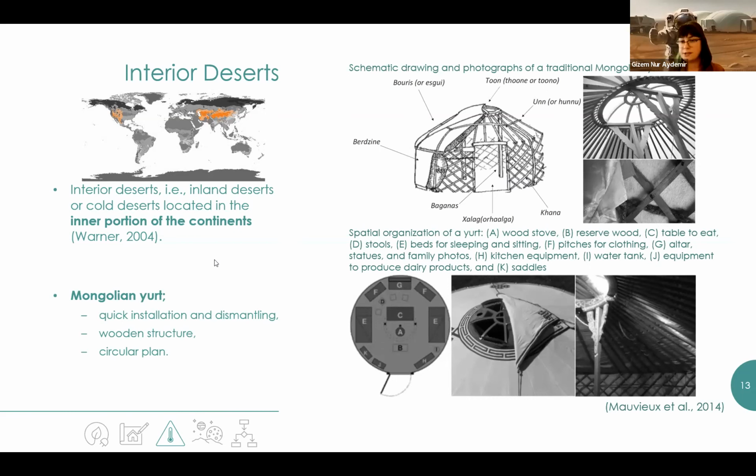In the yurts, tree branches are used for the frame and animal hair felt covers the yurt's trunk. The wooden tono located at the top of the yurt provides smoke evacuation and helps with interior lighting. The yurt has a circular plan, reducing the forces caused by wind. And the cylindrical body provides maximum enclosed space. And a hemispherical dome solves the problems produced by precipitation. The interior temperature of the yurt is adjusted by the openings and the fuels burned in the stove, which is located in the middle of the yurt.